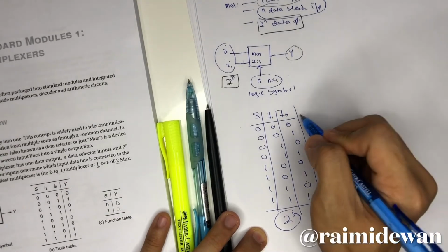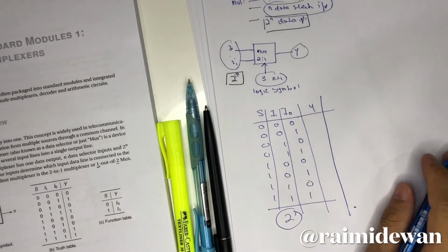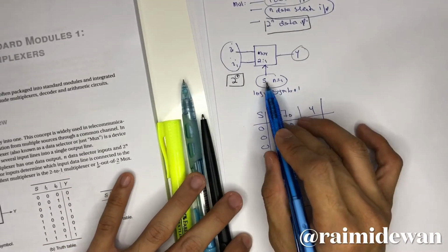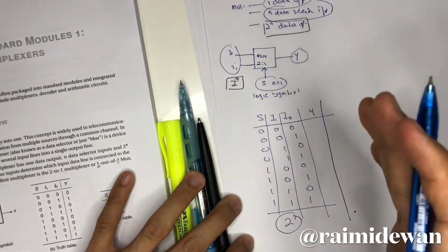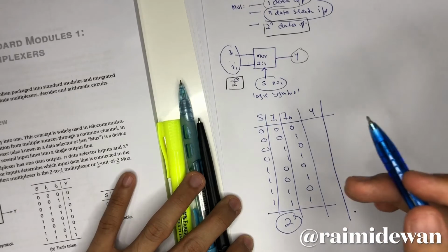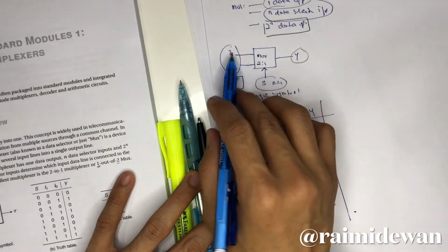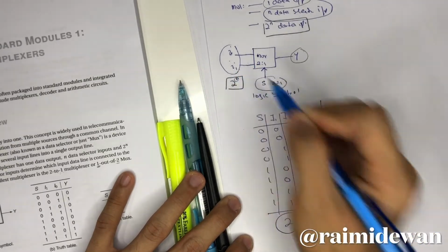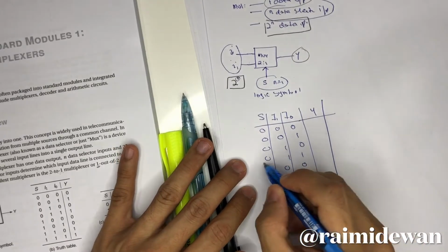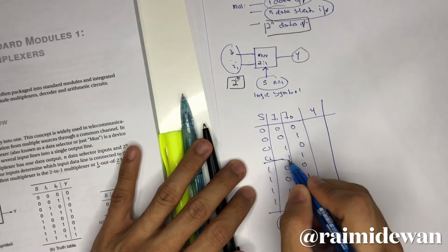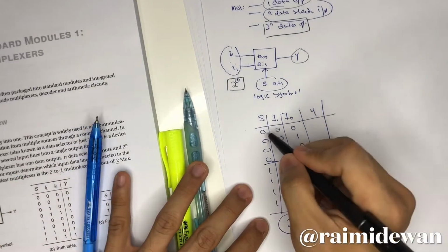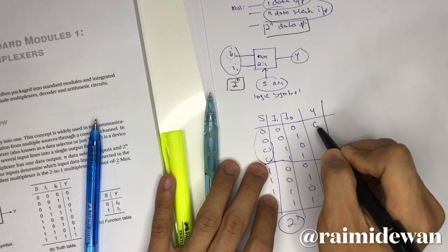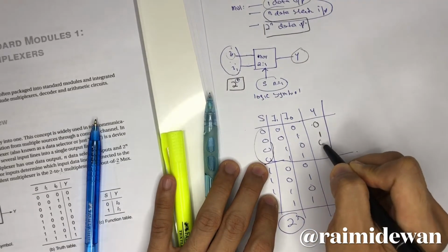Now, let's say y is your output. In the data selector, it can have two values, either 0 or 1. If it's 0, it will choose the value of I0. If it's 1, it will choose the value of I1. Let's make some boundary first. If S is 0, it only considers I0, so here you have 0, 1, following I0.